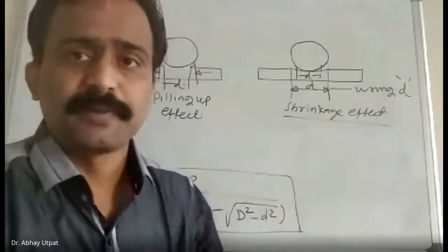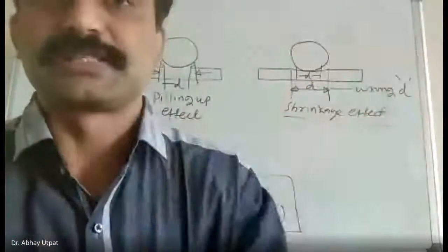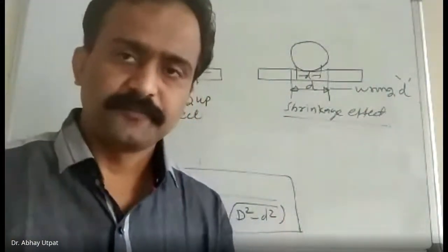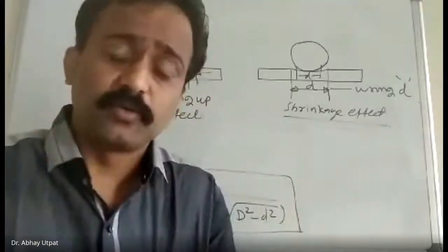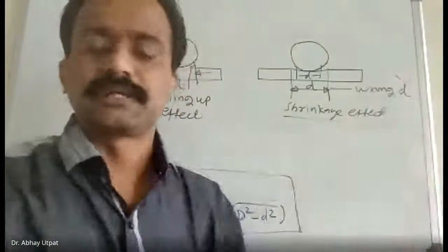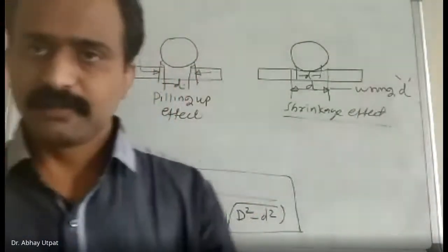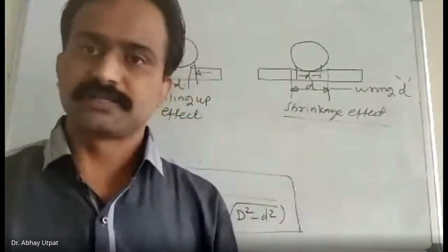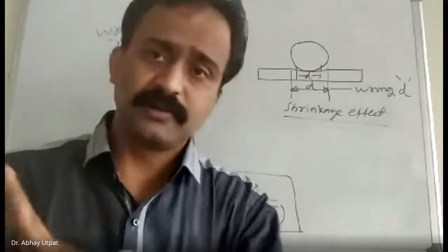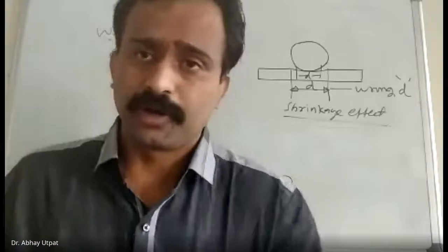Always remember, in case of these hardness tests, load and indenter are an oral question or MCQ question. What are the loads and indenters for a given test? I repeat, we have just studied Brinell hardness. You have to tell the standard load only. Don't tell the reduced load at the laboratory level.